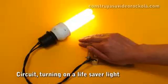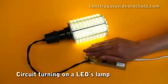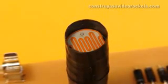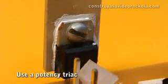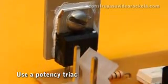This circuit operates with voltage from 115 to 220 volts, no need to make any changes. You can light a bulb up to 100 watts. If you want more power lighting devices, you should only change the BT136 triac for one that supports more amps, such as the BTA08-600, which supports up to 8 amps.